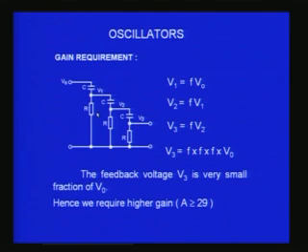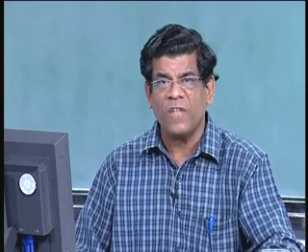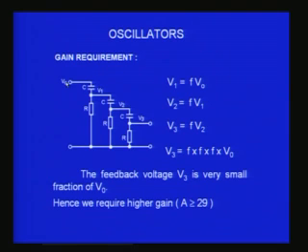So what happens? If V1 is 50% with reference to V output, then V2 will be again half of that, that means 1/4 of V0. If every one of the networks gives 50%, let us assume, then the first network will give half of the input, the second network will be 1/4 of the input V0, and the third will be 1/8 of this.